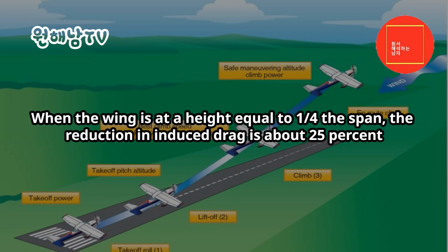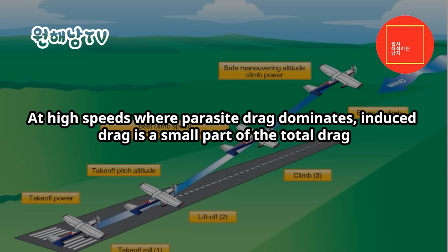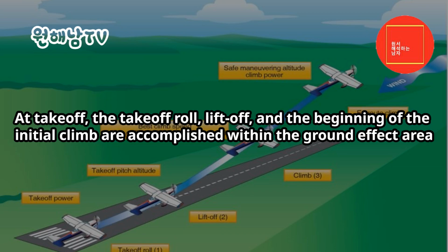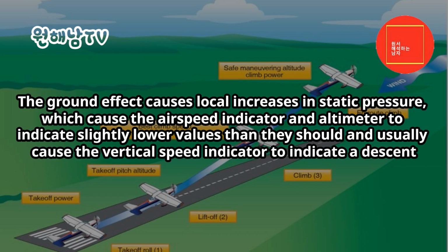When the wing is at a height equal to a quarter of the span, the reduction in induced drag is about 25%. At high speeds where parasite drag dominates, induced drag is a small part of the total drag. Consequently, ground effect is a greater concern during takeoff and landing. At takeoff, the takeoff roll, liftoff, and the beginning of the initial climb are accomplished within the ground effect area. The ground effect causes local increases in static pressure, which cause the airspeed indicator and altimeter to indicate slightly lower values than they should, and usually cause the vertical speed indicator to indicate a descent.